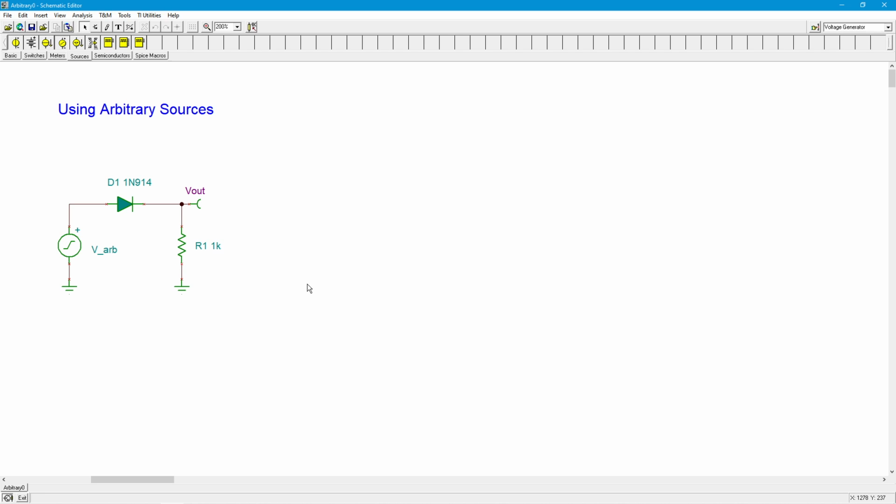So you could use something like this to check out the way in which an amplifier clips. Maybe you're working on an amplifier that does soft clipping, and you want to see how it really responds to a true audio signal. You could take a little recording of a guitar or a bass or something like that and run it through and actually look at it.